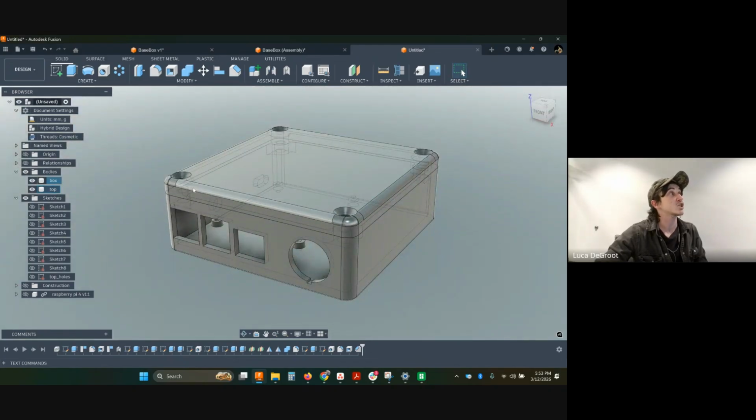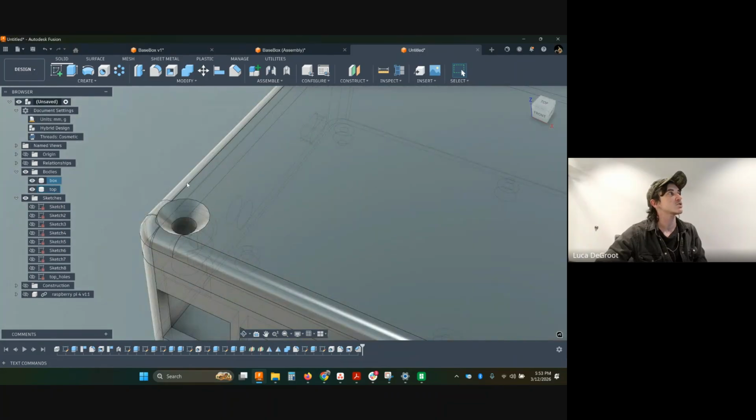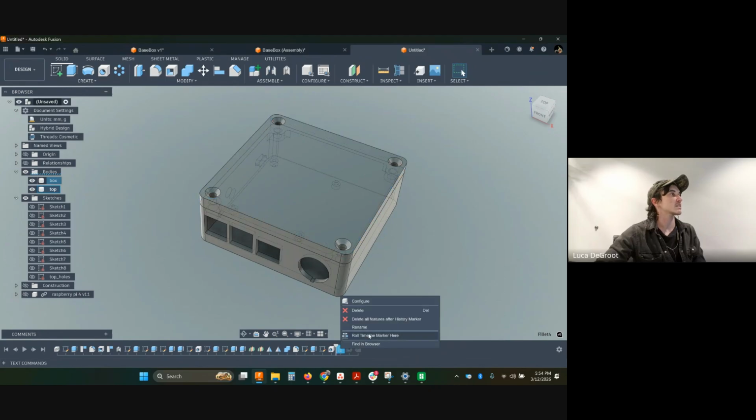Similarly, if I'm designing around machining, I don't want to do big fat fillets like this. This becomes actually a very expensive, annoying toolpath to make. If I am going to do it, I'm going to design this to be some standard dimension. So like 6 millimeter radius or 3 millimeter radius or 1/4 inch or 1/8 inch. I would say use inch sizes here, just because it's easier for us to get inch tools here in the US. So if I didn't want to make this big chamfer, I could suppress this.